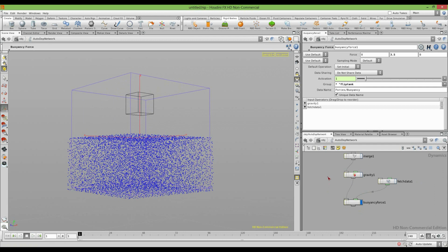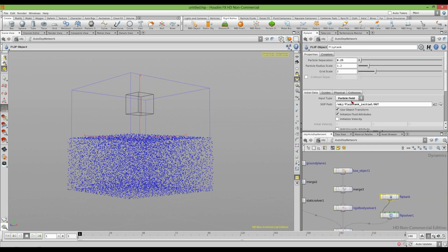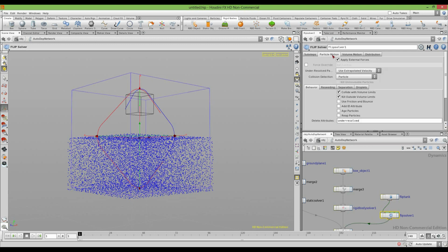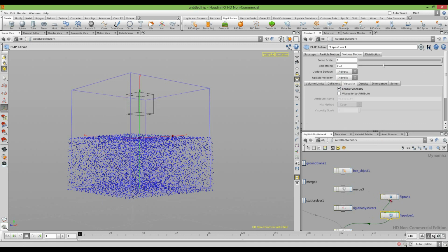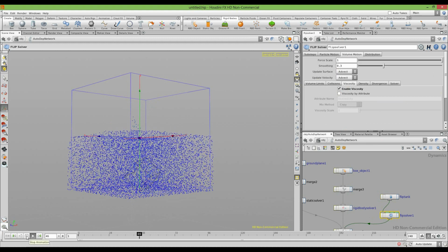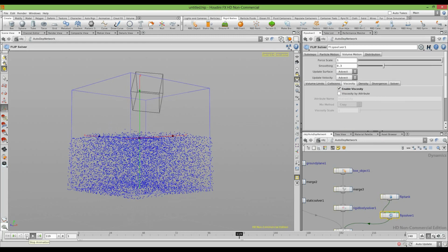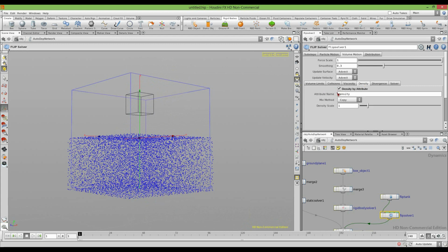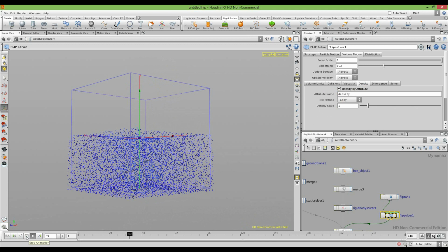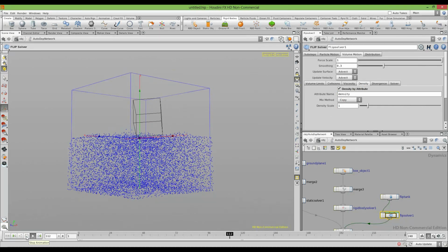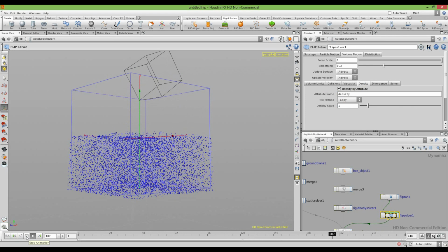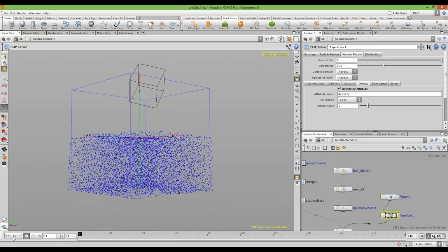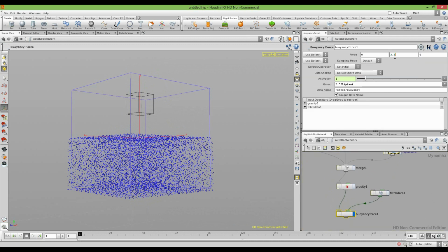Okay, one thing we can try is add some viscosity and density to the liquid. And you can do it in the physical tab. So let's say viscosity is really small, something like this. And don't forget to turn on viscosity in the solver, like so. So now you see that the cube behavior is smoother, but still the lifting force is too big. Okay, and turn on density to see how it works. Okay, now the lifting force, well, it feels like plastic. So yeah, as I told, it's really tricky to make it work. But you get the idea, and you just need to find the number.